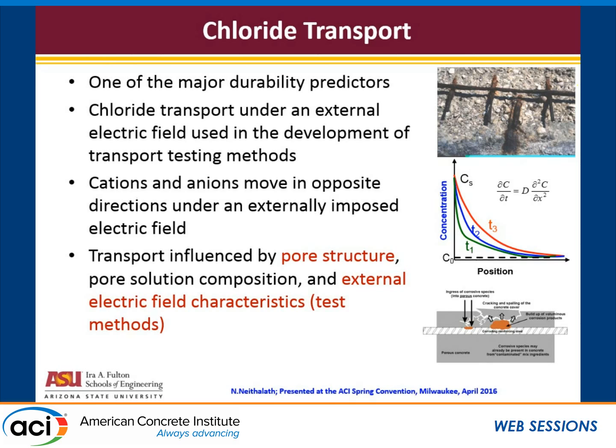So if you are subjecting your concrete to an accelerated test where I have a chloride saturated solution on one side and a chloride deficient solution on the other side, I put an electric current to make chlorides go through, we always thought that chlorides were the only things that were going. But your concrete pore solution doesn't have chlorides alone. It has a lot of other things, other ions that are very happy to move under electrical potential.